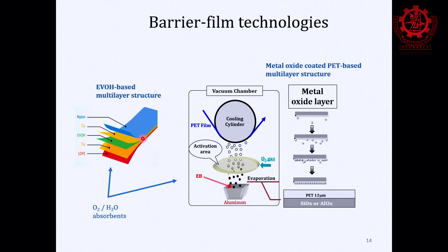mechanical, thermal, and gas barrier properties, because one kind of polymer cannot give you all the properties. Some films are good in sealing, while other films are good in giving a barrier property. They give you a very high barrier property, but you cannot seal them very easily. Yesterday we saw that sealing operation in one of the labs. That was polyethylene. It was very easy to seal, or polypropylene, easy to seal. But if you have PET or EVOH based film, it's not very easy to seal. So in order to have sealability, we provide inside either polypropylene or polyethylene film.